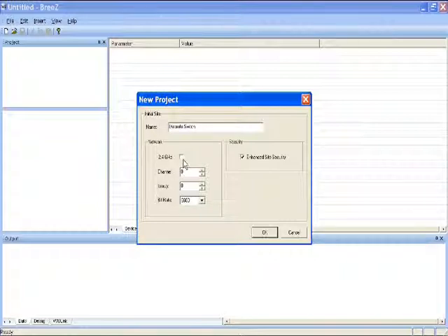The 2.4 GHz checkbox is for overseas hardware only. The channel availability is up to 9. The group availability is up to 999. We ask that you set this as you wish, but dial away from each other if sites are closer than 2,500 feet. The bit rate defaults to 9600, but can be set at 115,200 if needed. The enhanced site security should remain checked, and this will preserve your data and not allow sites to crosstalk. And then click OK.